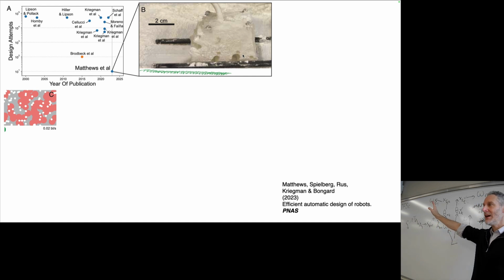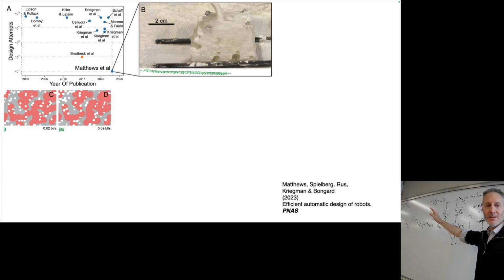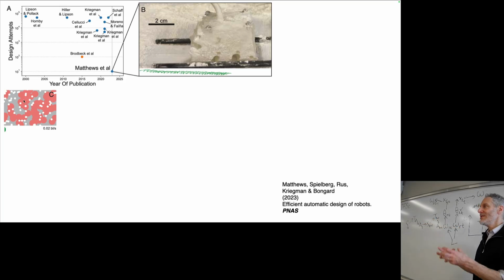You can see in the real robot where gradient descent is going to take us, but I'm going to show you in a moment how it got us there. So we added the holes so gradient descent could play with shape. And we added the red, the internal cavities, to allow it to play with where actuation goes in the body. Where does the pressurized air go? And when the pressurized air leaves those areas, how does it pull those parts of the body together?